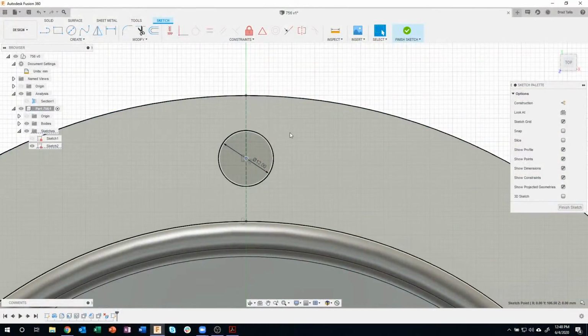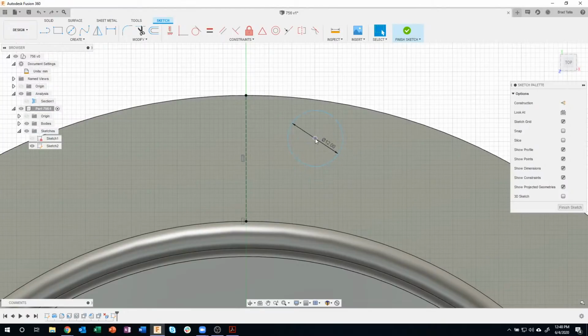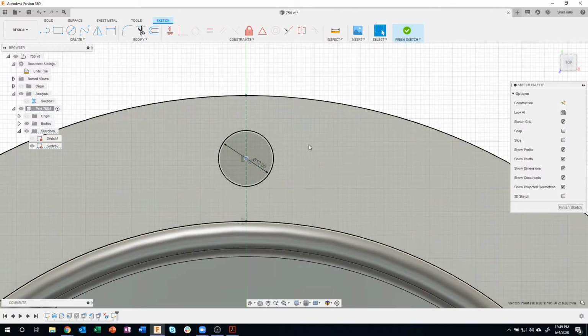There's two methods here. I can physically say, I want this to go from midpoint to this point here, and I see I'm actually clicking those two points. Or I can just drag what I want, and Fusion is going to try and build those constraints for me. Some people like to visually see, you know, I'm way out here. I say midpoint from here to here, and I even click way up here, knowing that, hey, it did snap to the midpoint. Or you can just, if you're comfortable with this, get it near and see it snap and drop, and then confirm that that is definitely the midpoint.